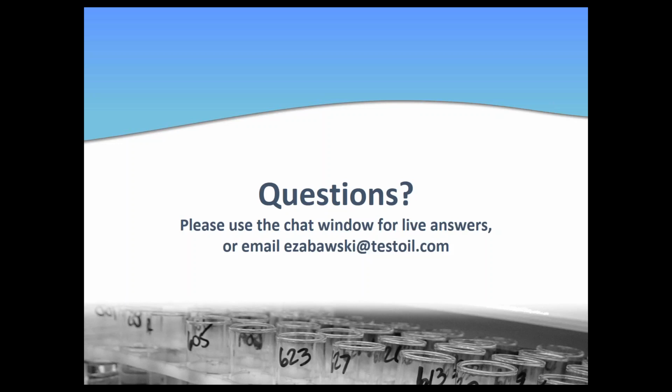The next question I have here is from Carmen. It says, do you have experience with the Karl Fischer oven method? Yes, that is the method that we prefer to run. We do the ASTM D6304 procedure C, the oven method, where you heat the sample, and instead of injecting the liquid directly, we're heating the sample and taking the vapor that's coming off and throwing it in there.